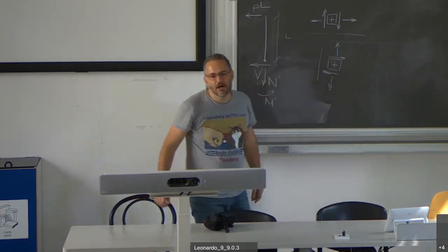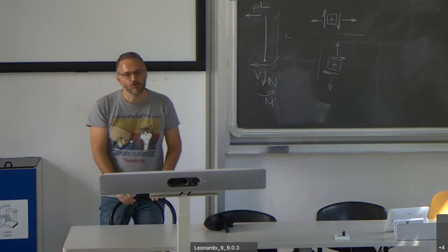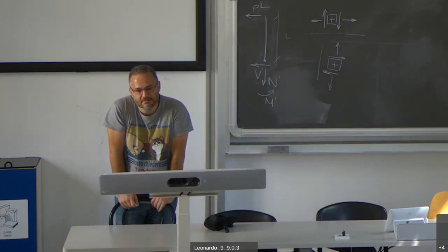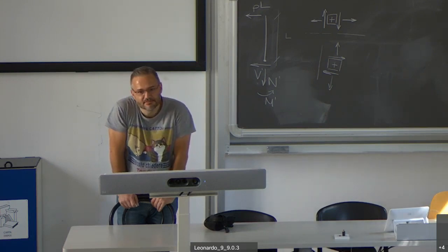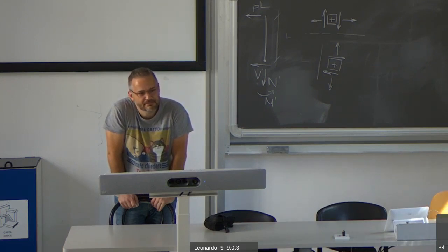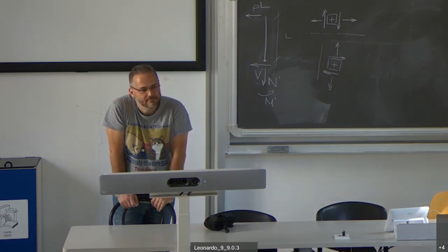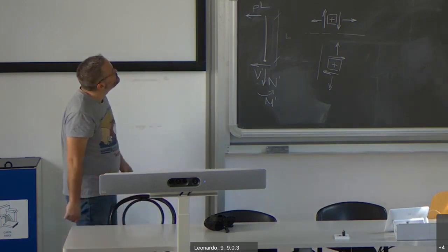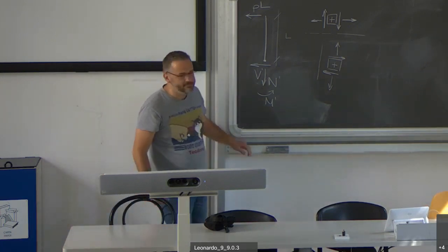Shear force. How is the shear force at the bottom of the left part? Clockwise, counterclockwise, left, right? Right. Clockwise or counterclockwise? Counterclockwise. It's correct. Well, how does the bending moment look like? Tension is on the left or on the right? Wait. Because that's what we need to plot the bending moment diagram. Tension on the right? Tension on the right. Yeah, looks like it.